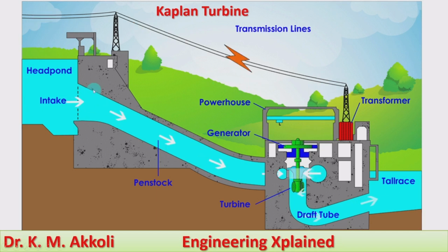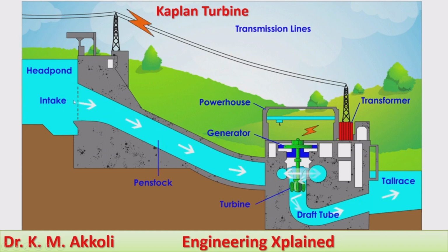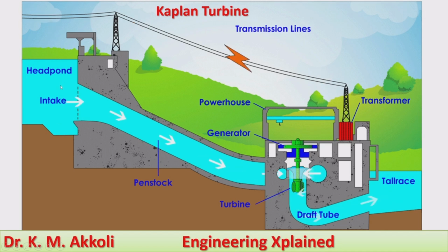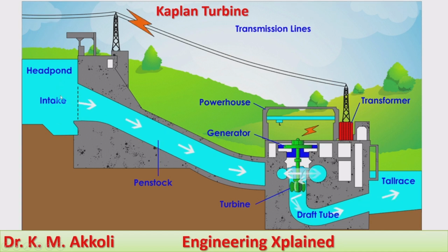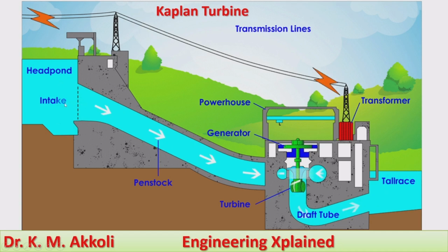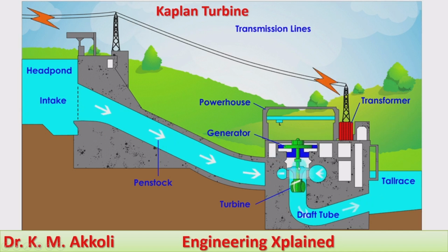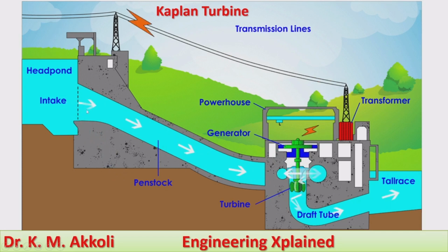It requires a low head. Even about 2 meters of head, this turbine works. The head range is between 2 to 25 meters. That's the vertical height from the turbine level that is required.